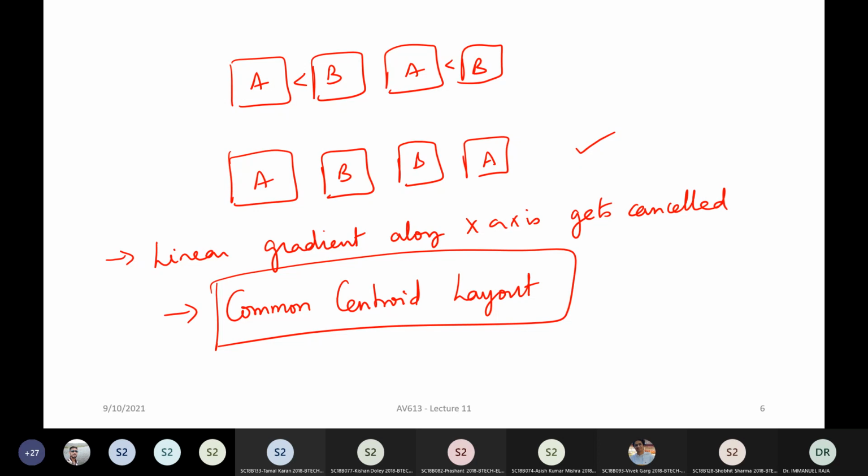Now, whenever you have current mirrors in the industry, of course, current mirrors are used in pretty much all analog circuits. So you basically will have one big circuit and a bunch of PMOS current mirrors and a bunch of NMOS current mirrors. Usually they will say, okay, all the current mirrors put together, you will do a combined layout, and they will be common centroid layout.